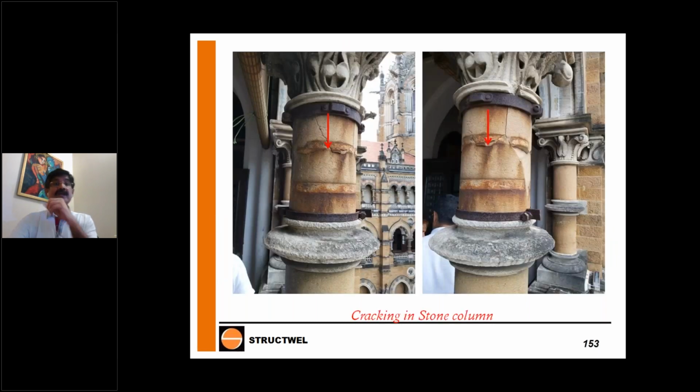Now, today, what I'm facing is a different type of challenge. These columns are cracked. This column has a mild steel pin inside. This is a stone column, which is connecting this stone to this stone. And the mild steel pin that is inside is corroded. It is swelling, and because of which it is pushing the column outwards. So it's a great material and structural engineering challenge.